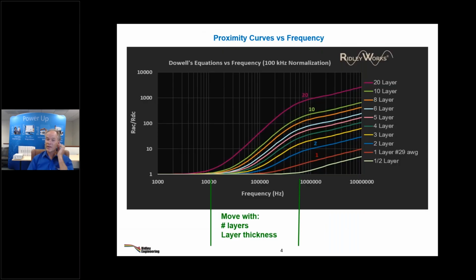Yeah, that's a really good question, because yes, we've got these nice curves that show you what the AC resistance is doing, but when we build a switching converter, you have all different components in there. So you have a DC component, you have the 100 kilohertz component, if that's your switching frequency, then you've got 300, 500, 700, 900, it just keeps on going. So every topology has to use these curves differently, because it will hit the curve at different frequencies. And then you've got to multiply the AC resistance at that frequency times the RMS current at that frequency.